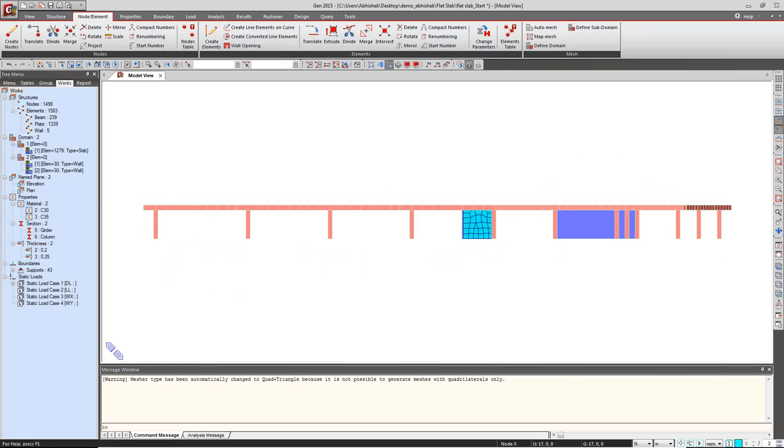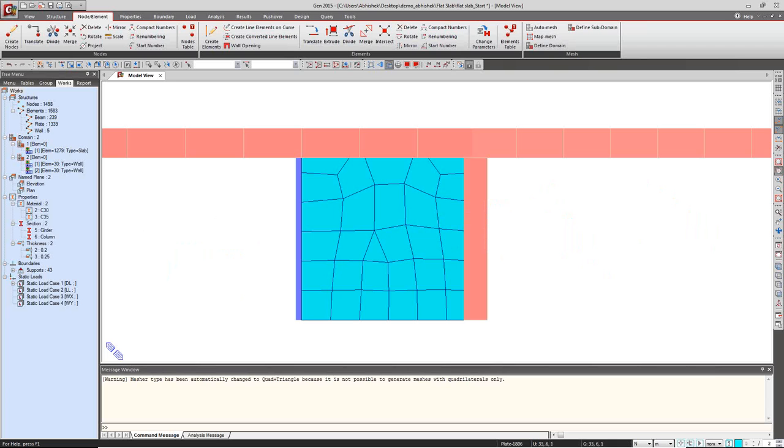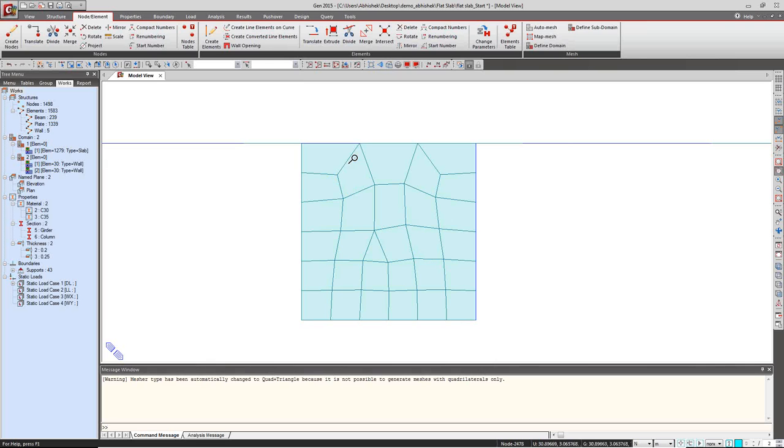Now you can see, see here, initially my size is 0.5 by 0.5. Once it goes above, that size is increasing. Why is it increasing? Because according to the nodes that are there, my program, see here, these are my slab points, these 2 points, because it's 1 meter by 1 meter. So according to these points, it's automatically merged and it automatically generates that element. So no need to worry about these joints and these things. The program automatically considers these things itself.